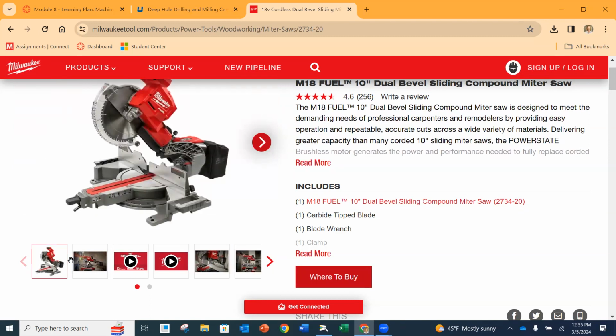So there's a bolt in there and a nut, and then they use one Belleville washer to spring load that system to keep it clamped. So when you rotate it, it's preloaded, so there's not any play inside of it. So that's another application of a washer. And that's just a single washer used, bolted together in the system, preloads that nut and bolt, and it stays in there.